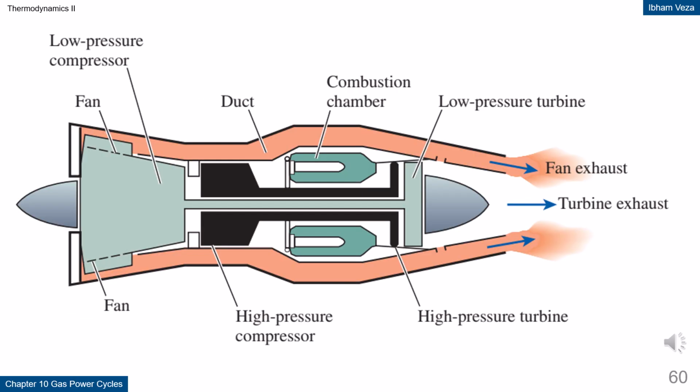Transition to fan-based jet engines. This part serves as an introduction to more efficient jet engine types for commercial aviation. The focus shifts from pure turbojets to engines with bypass flow. The basic concept is to produce thrust not only from hot exhaust gases, but also from cold airflow. In this way, propulsive efficiency can be improved. This prepares the ground for understanding turbofan and turboprop engines.